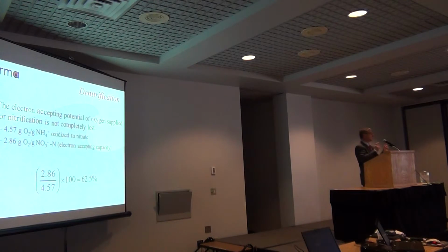Okay, so we're feeding so much oxygen to get the ammonia to convert, but that nitrate that's getting converted has an oxidizing capability of 2.86 compared to the 4.87, so we can recover it. It's like a 62% recovery in the oxygen that you've already spent.